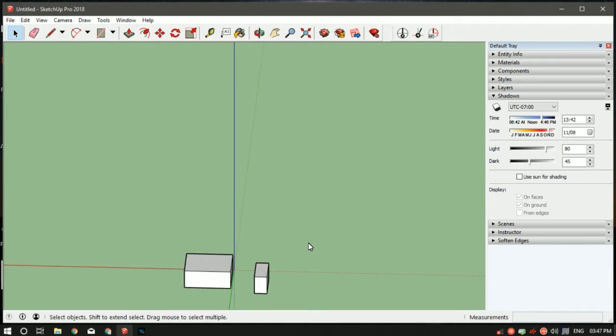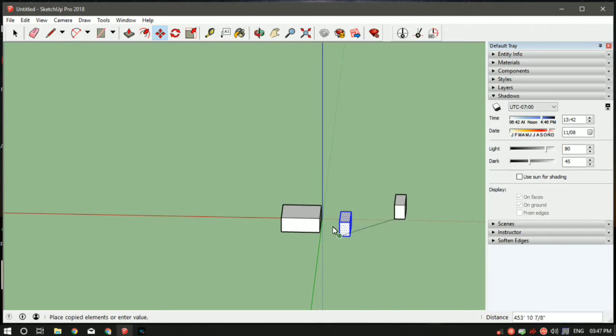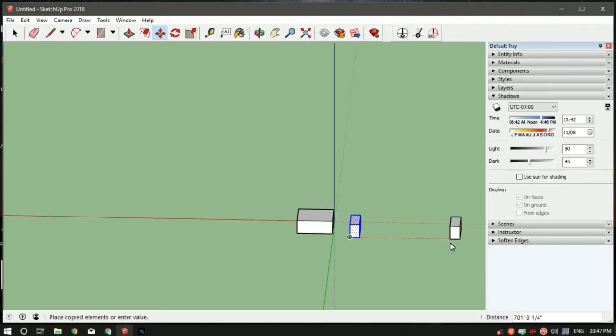Now I'll use the pattern tool in a different way. What I mean by that is, again, let me select the entire object. You have to first activate the move command. Shortcut is M, followed by control, and then select the start point. Then what I do is I want to make this rectangle. This is the first rectangle, and this is somewhere around 800 feet. From there I want to make the last rectangle 800 feet away, and in the middle I want 7 rectangles which are at equidistance from each other.